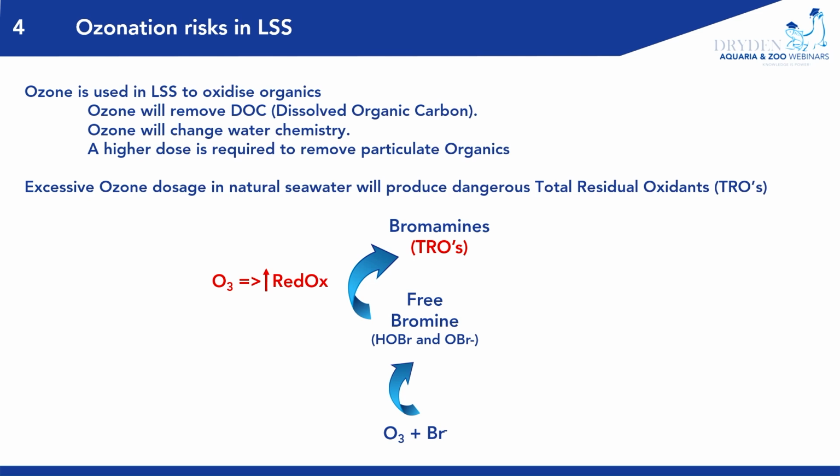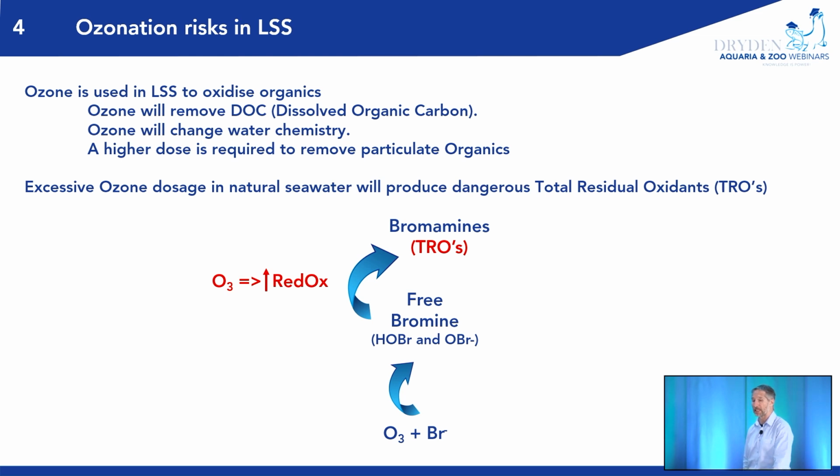So it's a massive savings in terms of ozone generators and input of that, maintenance of ozone generators, but more importantly, coming to the next point, and particularly in saltwater systems, where you end up producing bromamines through the application of ozone, the residual oxidants, so let's put that into the bigger picture of just all residual oxidants that are being created by ozone input, it can be very negative on the animals in the system. Either you're going to generate gill burn, problems with skin lesions.